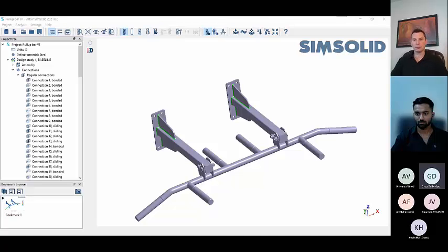And Ali, you were very cruel to SimSolid. It's much more accurate than 95%. As you said, it's a part-based solver, so it does part-based equilibrium and part-based stresses. Where SimSolid doesn't always give you the best answer is where the local stress is governing the design, and in your benchmark there were the stresses around the hole, because SimSolid doesn't put a whole bunch of math in to capture that. It's not meant to capture the details, it's meant to capture the global part behavior, so it's really accurate when those are the problems you give it. It's never really meant to be a detailed stress solver, so that's where the numbers bring the average down, but that's not necessarily fair.